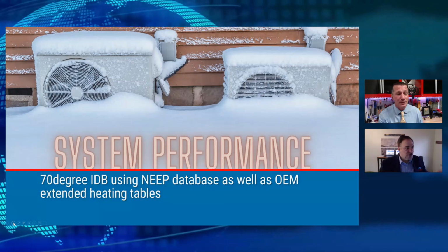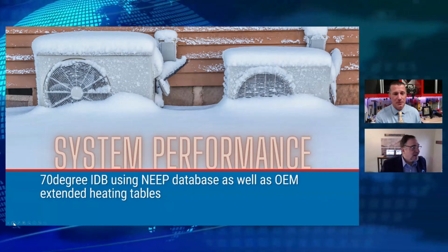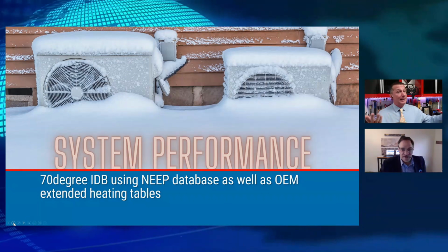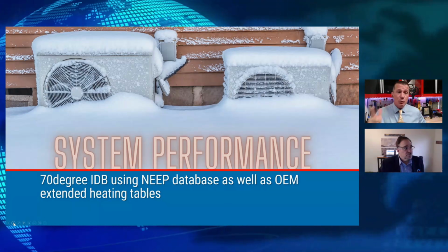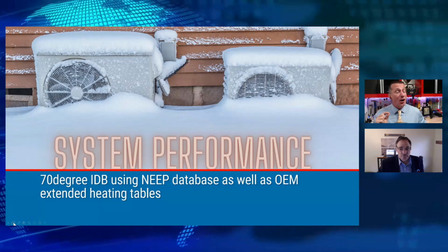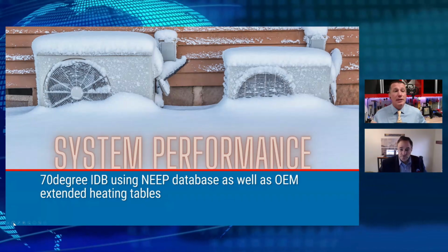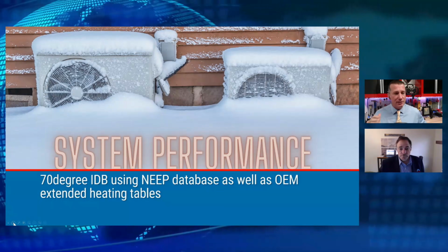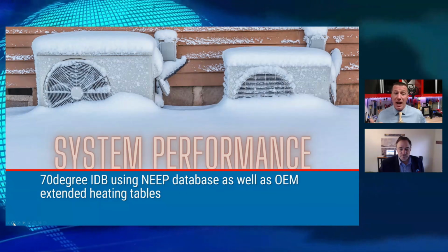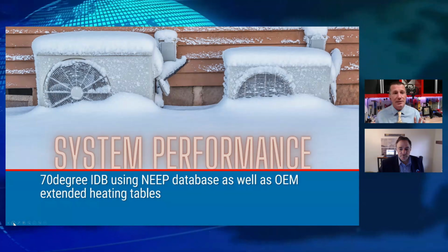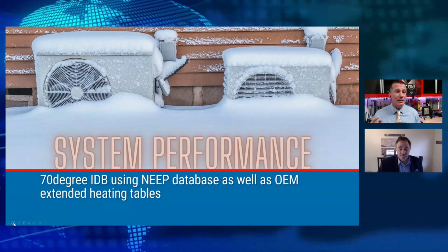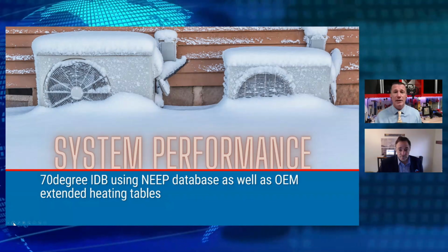We do have some questions here, Clifton. Sure. What we got, Howard? I've got a lot of them, but we could take them little by little. Yeah, do all heat pumps continue running no matter how cold it gets outside? Good point. So that's where this comes into play. When we're talking about inverter-driven heat pumps, they are not all created equal. Some of them will actually shut off at 5 degrees Fahrenheit. Some of them will shut off at 0. Some will shut off at -5, -10, -22. It depends on the design of the manufacturer. And we're going to look at some of these tables here in a second so you can see exactly where those are, so you can start comparing different products.